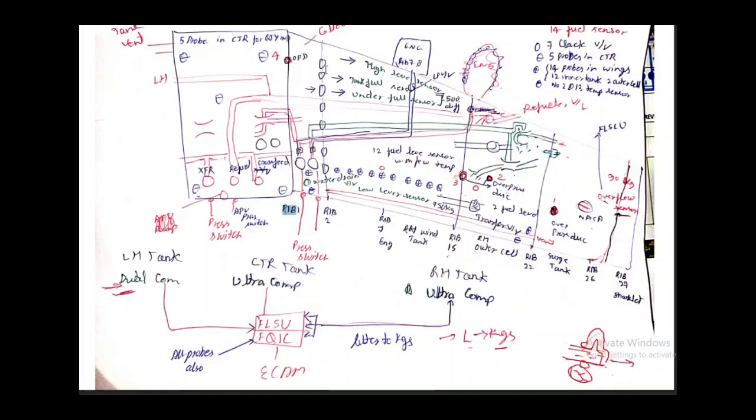And here you can see I have drawn something like this. This is your clack valve. This also will go into detail in the fuel ATA chapter. So the clack valve, what is the purpose? Why is it installed on rib 2? This is a very good question, and this is very interesting. Why is it on rib 2? Here also there is not only one. It is around 7, 3 plus 3 is 6, 7. In total 7 clack valves are there.